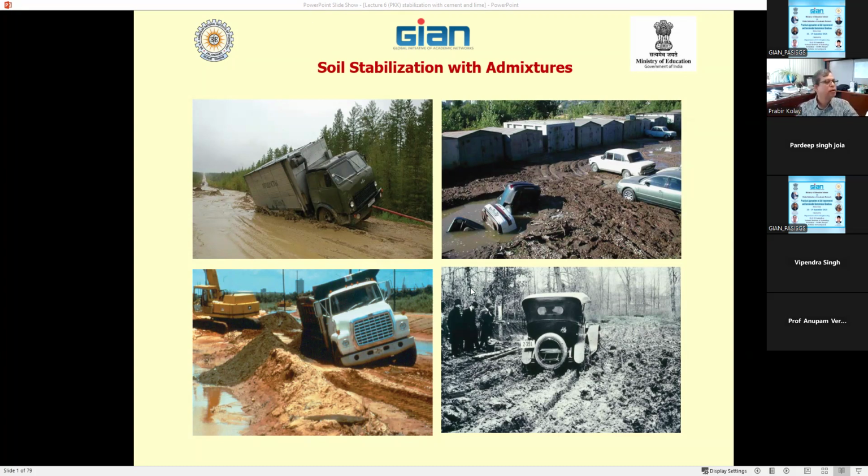So again, welcome back. Now I'm going to talk about soil stabilization. As I mentioned earlier, there are four major soil treatment methods. One is mechanical, one is hydraulic modification, getting rid of the water, then chemical modification, and the last one is inclusions, or using geosynthetics. Today I'm just going to talk about soil stabilization with admixtures.